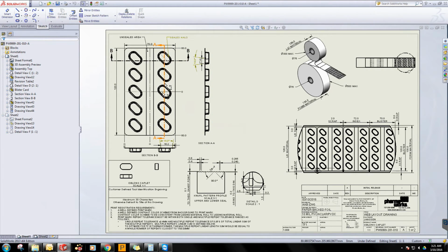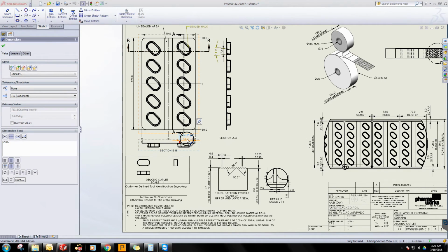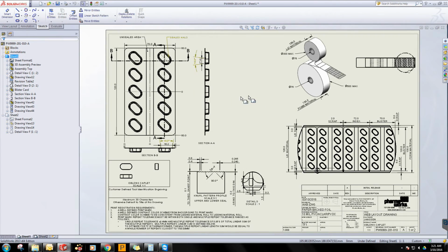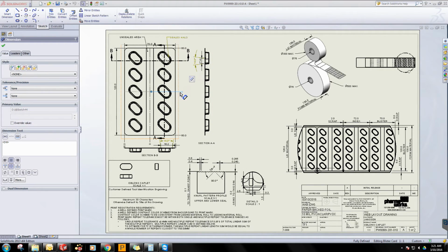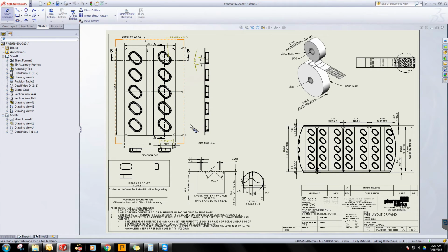What we're going to see here is a couple of things. The card length and width are automatically going to be put on there, but things like your theoretical sharp point and that distance are not going to be automatically included, and also your ordinate dimensions here. These values are easy to add. You will have to add them.